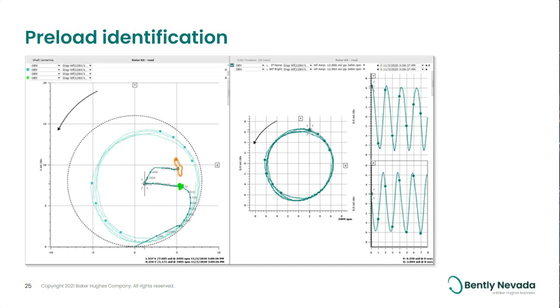If you look closely, you'll see the green is a small orbit back when the system is fairly well pressed against that wall, and also that orange orbit. Again, we've moved the preload frame so that it is kind of against the wall of the bearing, so it's kind of constrained. And that's what you're going to find when you look at the shaft centerline plots.